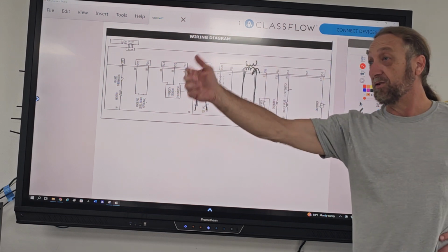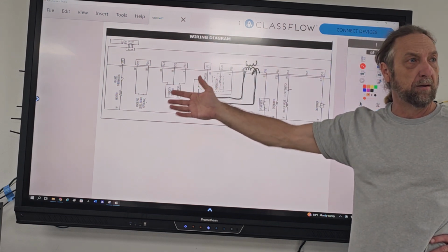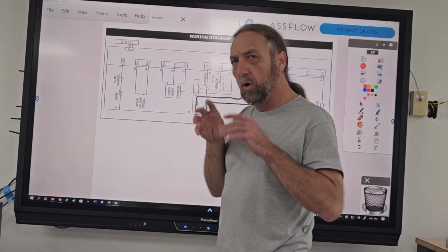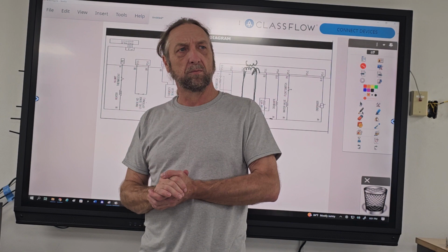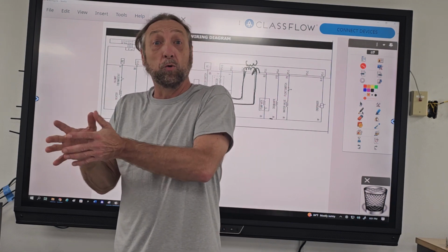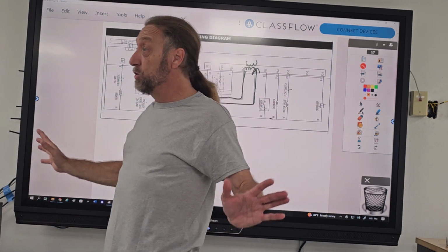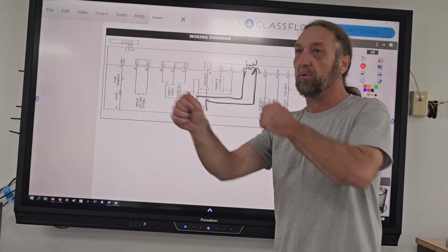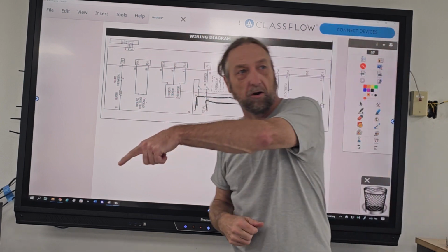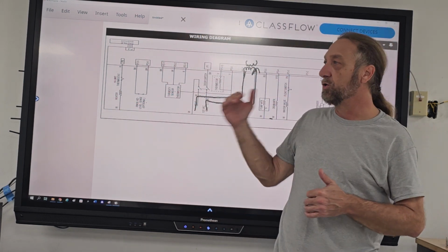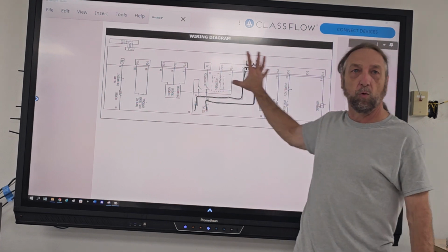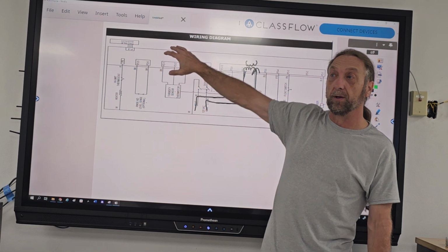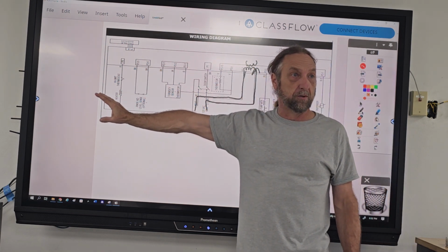Well, if you close the door, you press start, it's going to continue from that minute, right? So is the power of the board in a microwave going through the door switch? No. Otherwise, the board would lose power, which means it would lose the program memory, and it would start all over again, and you'd have to press cook, time, start all over again. So the door switch doesn't control the power for the board, but it does go through the board as an electrical circuit for these components.